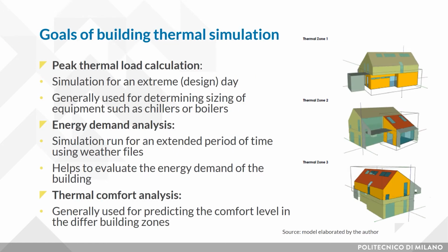As already discussed in the previous lecture, building simulation software can be used for different purposes: peak thermal load calculation, energy demand analysis, and thermal comfort analysis. In peak thermal load calculation, simulations are normally set for the extreme design days and generally used for sizing equipment such as chillers or boilers. Regarding the energy demand analysis, simulations are conducted for an extended period of time, normally a season or a whole year, using a weather file with the aim to verify the building response, such as energy demand, to the entire range of conditions expected at a particular site.